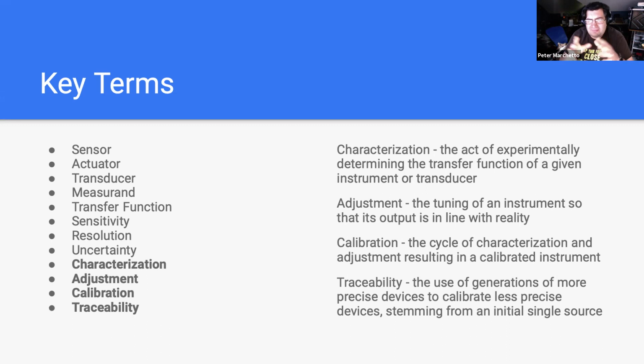So we usually got, I think, a bimodal distribution centered around 10.75 and 9.25 centimeters. So it was definitely obvious to even the casual observer that 10 centimeters was not 10 centimeters by the time you got 10 generations out. And that's exactly traceability. This is a matter of bringing the measurement that we know is true through a number of different noisy systems, or in this case, a number of different measurements and other cyclical references, out to the eventual measurement that we're making.